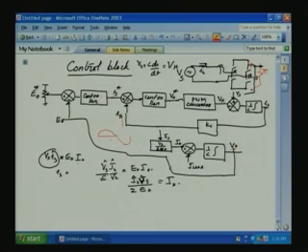But we want unity power factor. So, this IS should be in phase with Vs. So, we should generate a sinusoidal reference waveform in phase with this one with unit amplitude, and we should multiply it with this IS and give it here. So, we have to modify this part. Let us see how we can do that. So, the controller has to be accordingly modified. The controller output is here.